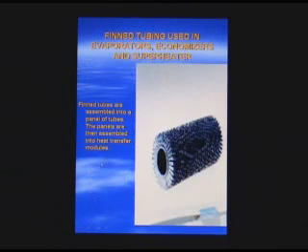Here's a better picture here. This basically is an example of a fin coil that's used to enhance heat transfer. Rather than the circumferential fin that the air coolers have, these are more rugged. They're pin-type fins. They have a high heat transfer coefficient available, and they are also designed to survive in the hot gas environment with supplemental firing.